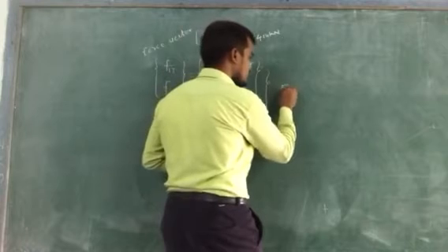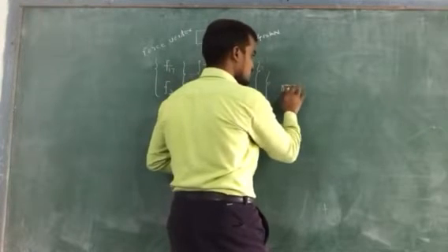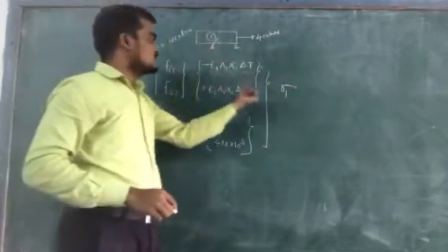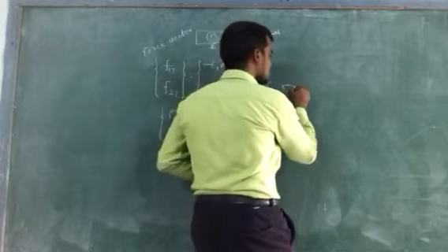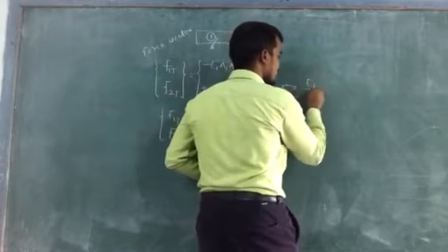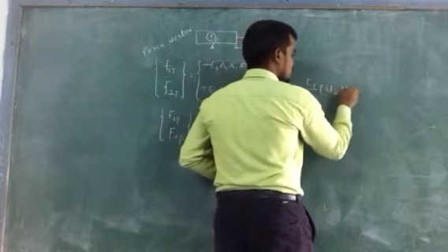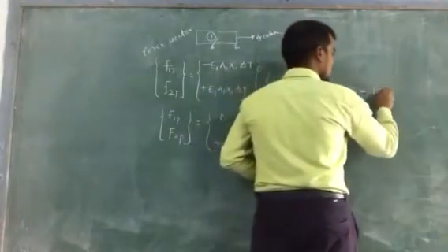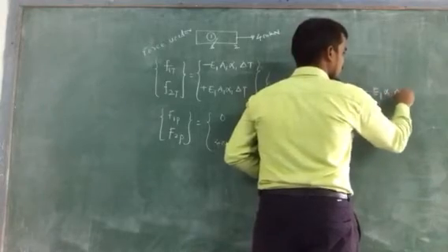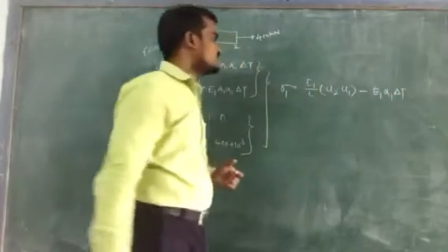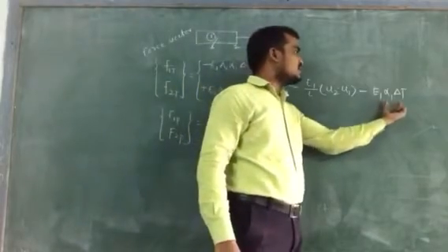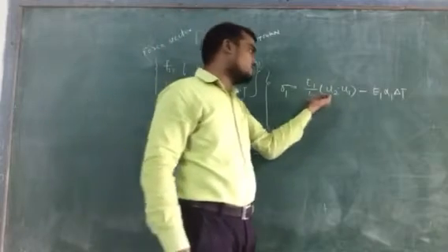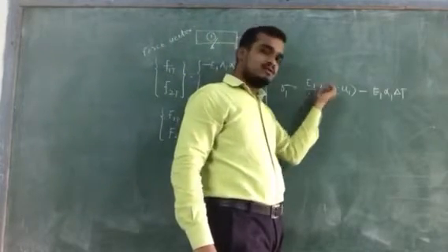If we are asked to find the stresses in this element, then sigma 1 will be similar to the previous case, E1 by L1 in bracket U2 minus U1, and one term is added here, minus E1 alpha 1 delta t. You just need to subtract this E alpha delta t term from the previous method, as we already derived this term in our previous lectures.